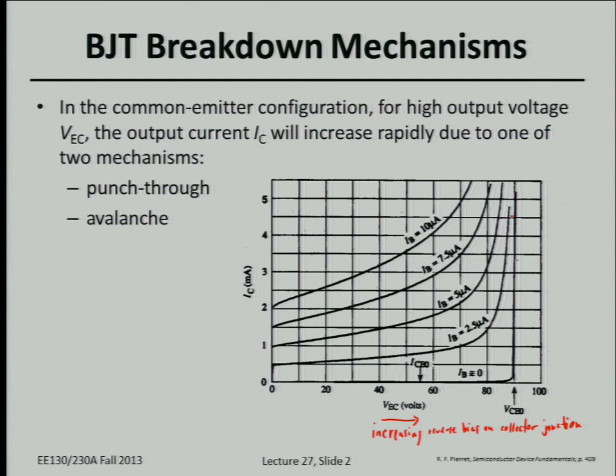So usually, do you remember the avalanche breakdown for a PN junction? It was pretty abrupt, right, basically. So these curves here, this abrupt increase right here, this would be due to avalanche. So anytime the current is increasing rather abruptly, that's a characteristic of an avalanche mechanism taking place. And this more gradual increase in current with voltage is then more likely due to punch through.